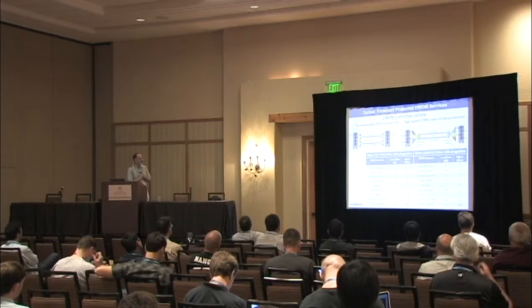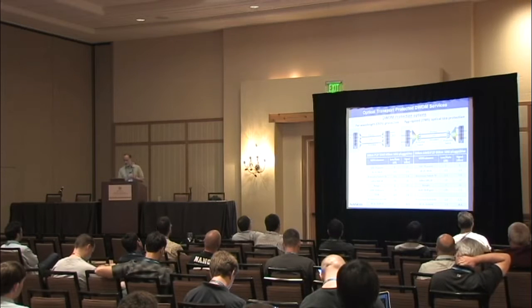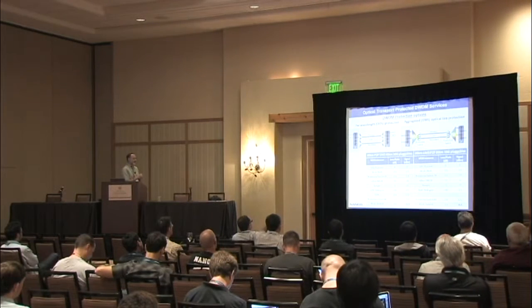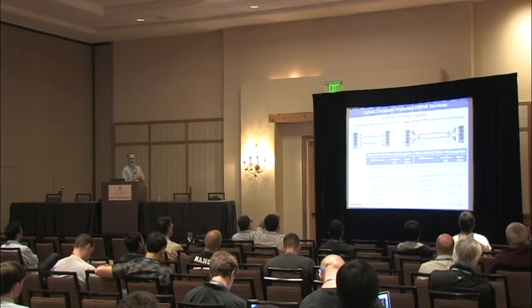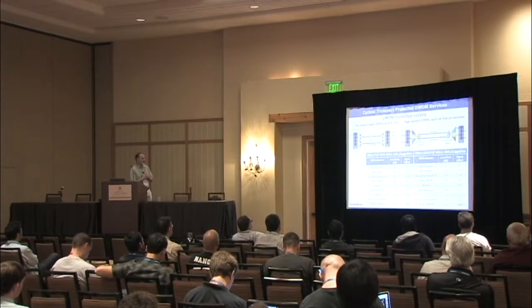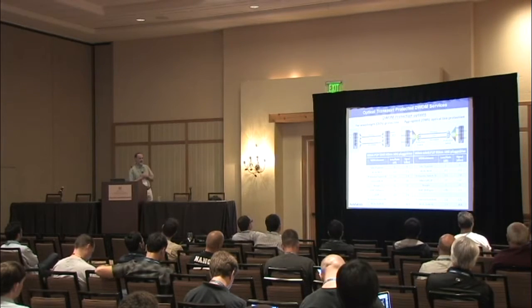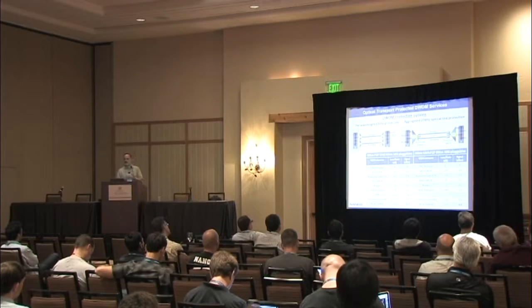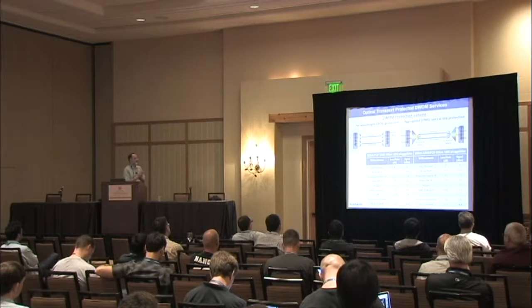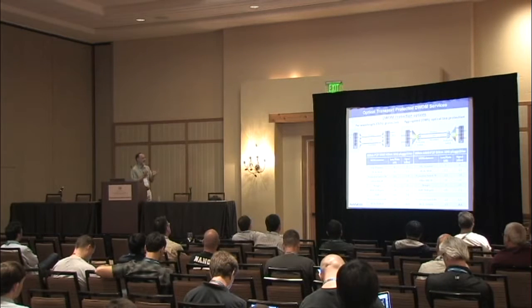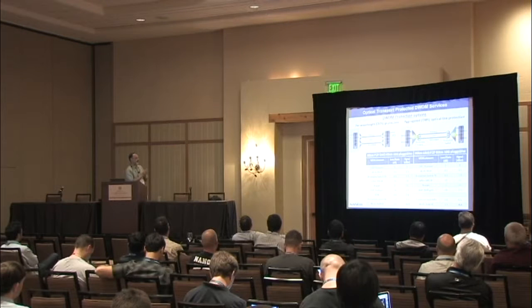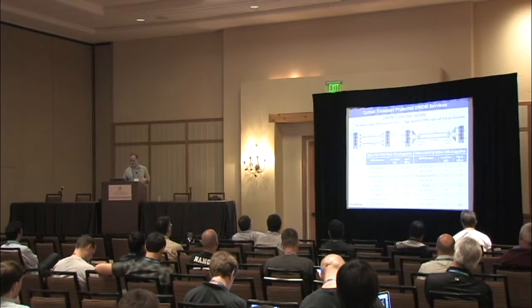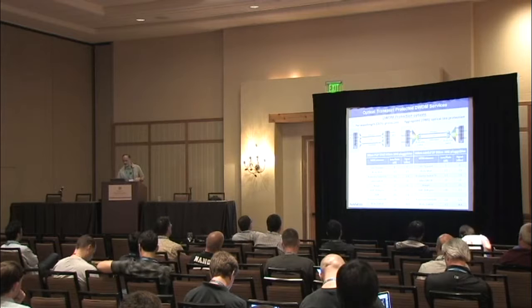So we are good. We can do the same using the 80 kilometers, and the only difference is that we don't need any dispersion compensation, so that line is blank, and I'm at minus 8. So again, within the active range of the receiver, we are good. Again, in these cases, it's theoretically possible to do the 40 kilometer. I personally prefer the 80 kilometer option.